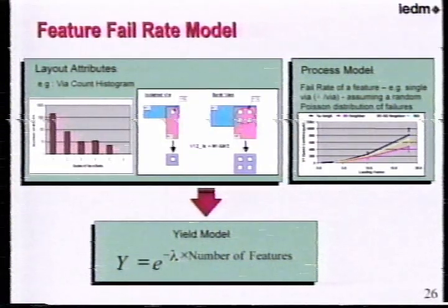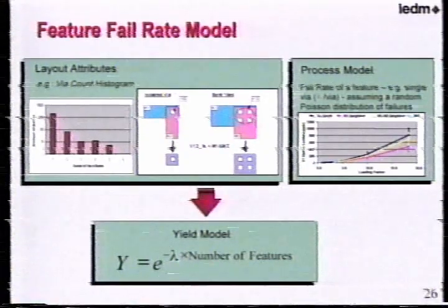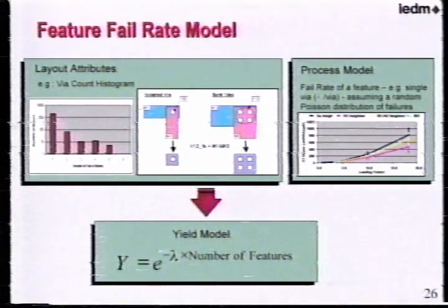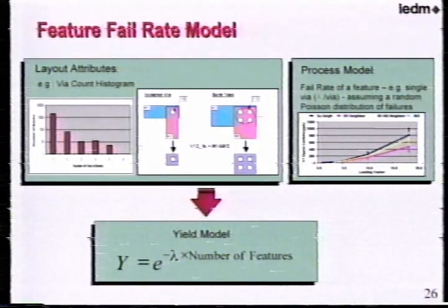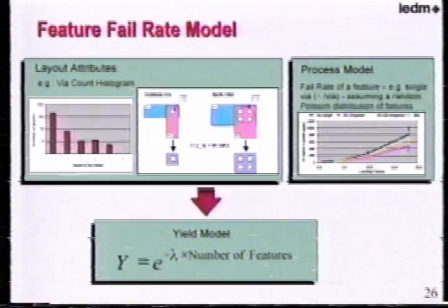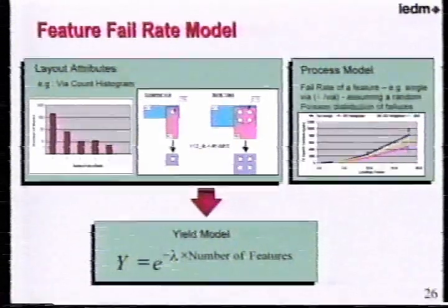Essentially what we are doing is we have cases where we have banked vias, we have vias which are at one edge, isolated along different metal layers, for example, the upper and the lower. And what we can do is we can take an attribute extraction from the product. That is, you can look at the product, you can count the types of vias that are banked, for example, count that are ISO, and then you are able to convolve it with this characteristic.